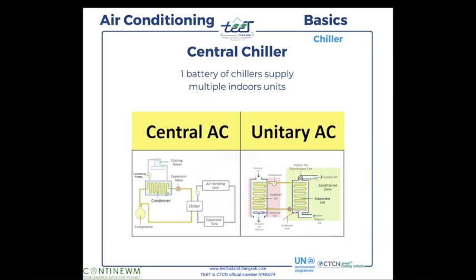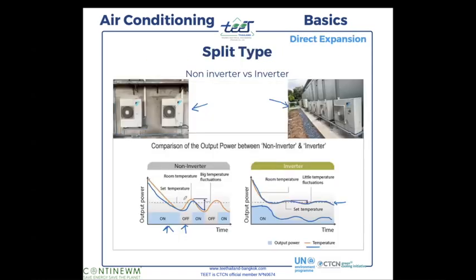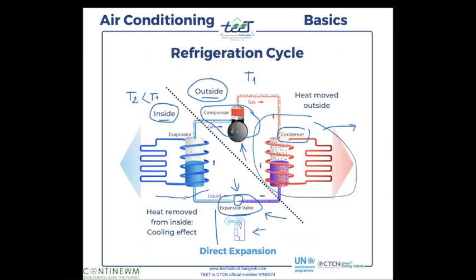But the principle is the same. What you have here, what does it look like? It looks exactly like the compressor of the split type we saw. It's exactly the same. The only difference is that the evaporator, this part here, in a direct expansion system, is in the air.